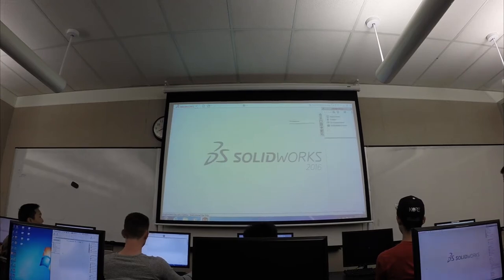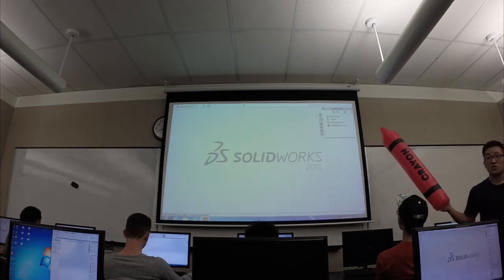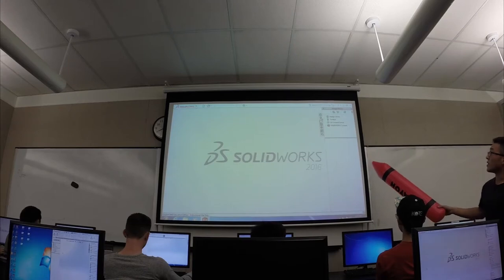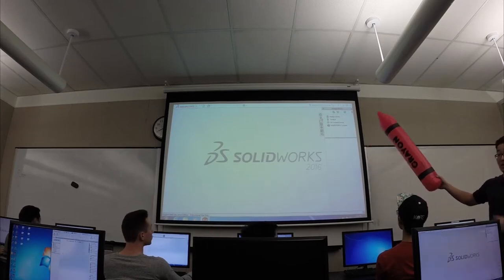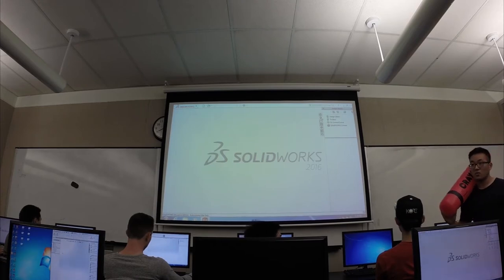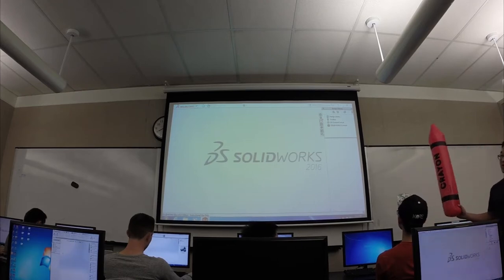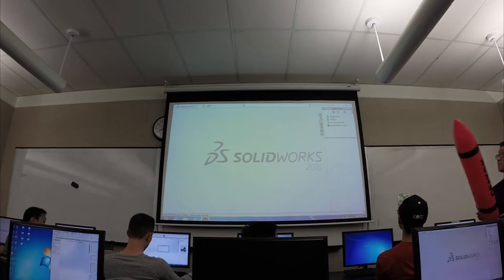As you can see, there are multiple tabs. The design library tab here is super cool if you don't want to design your own gears, your own belts, your own chains and stuff like that, right? The design library has a whole content of predefined parts for you to use. So if you're using, okay, I need a 38 teeth spur gear and a 12 teeth spur gear, right? It's a lot of time to go through the sketches to draw out a gear, making sure all your involute circles are correct. If you want to ignore that, you can go to the toolbox and download predefined parts.